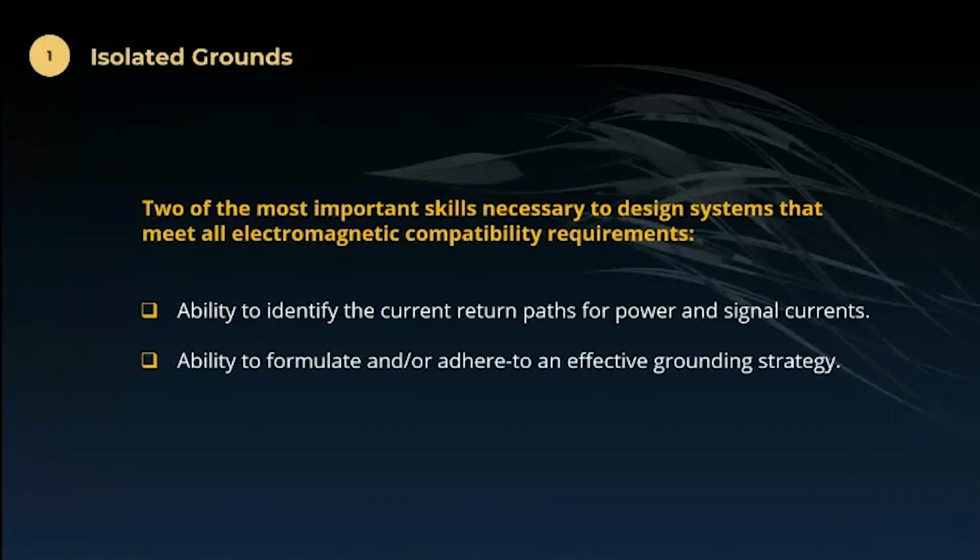And I mentioned current return, like in Dr. Bogatin's talk. Actually, Rick Hartley gave a talk for this same conference a few years ago, titled Grounding. And it was an excellent talk and very good advice. I'd encourage you to go back and look at it. It's as relevant today as it was back then, but it was really about current return, not about grounding. He was talking about how do we get these signal return currents back where they need to be without causing an EMC problem. And that's different from grounding. Grounding is also important, but grounding and current return are not the same thing.